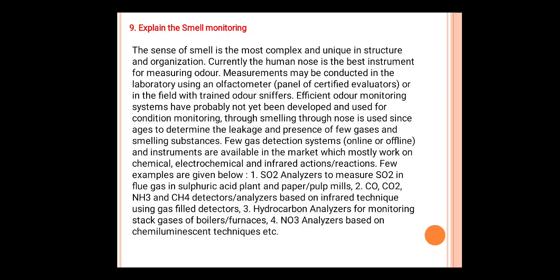Few gas detection systems and instruments are available in the market, which mostly work on chemical, electrochemical and infrared reactions. A few examples are given below. First, SO2 sulfur dioxide analyzers to measure SO2 in flue gas in sulfuric acid plants and paper pulp mills. Second, carbon oxide, carbon dioxide, NH3 and CH4 detectors and analyzers based on infrared technique using gas filled detectors.